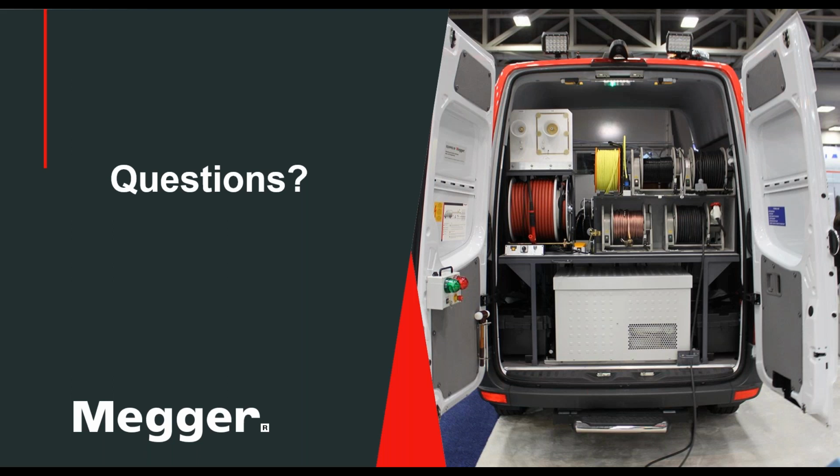All right, thank you. Maybe Henning, just one brief add-on. The ST25 will go to 30 kV high pot, right? So in general, it's a good thing to always check the breakdown voltage, even when you work on a 230 kV cable, because most of the time breakdown voltages, especially on high voltage cables, are fairly low because of the amount of fault current present, which really provides a fairly low breakdown voltage. So for the most part, you can find faults with a medium voltage fault locating system on high voltage transmission cables.